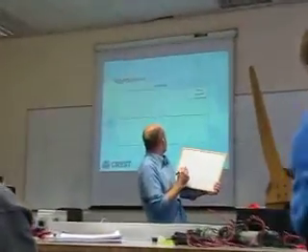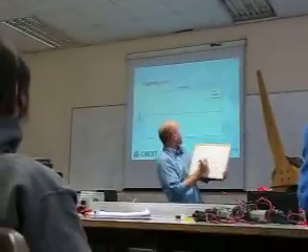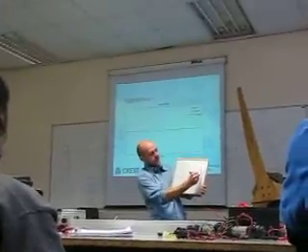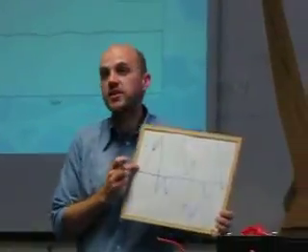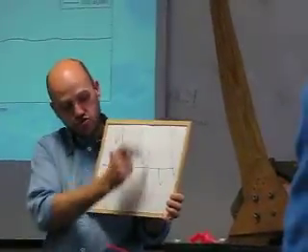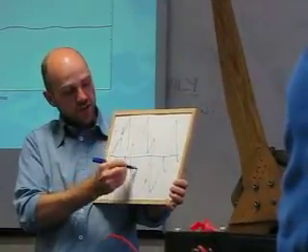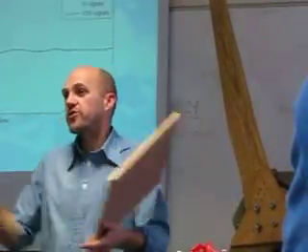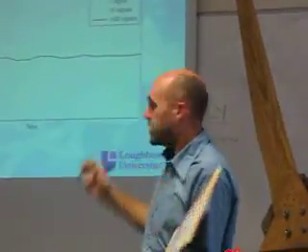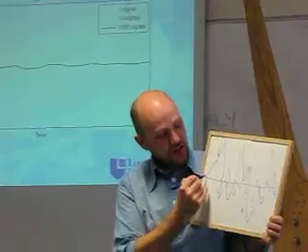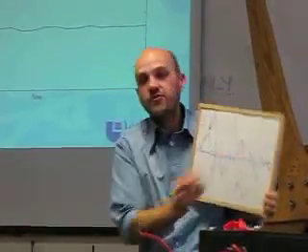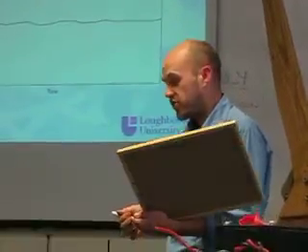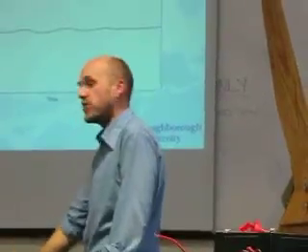Okay, so this graph is meant to show you if you've got just one input, you get huge variations. Say you had one wind turbine, the output would be everywhere. If you have 10 wind turbines, you start to add them up, because when one's generating, another's not, so they start to aggregate. If you add up 10 signals, you still get quite a big variation. If you add up 1,000 signals, you only get very small variation. That effect's called aggregation, and on large electrical supply systems, that's a very useful thing.